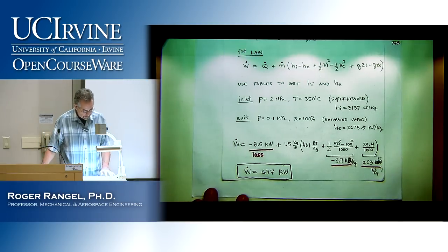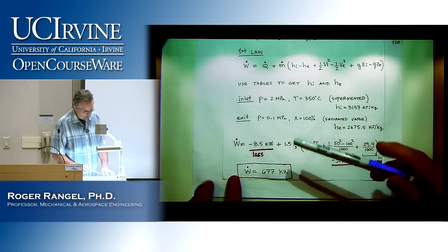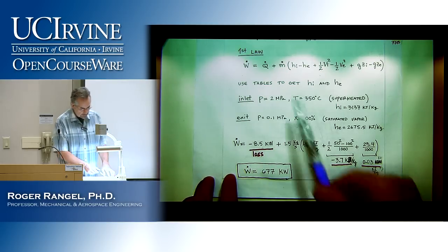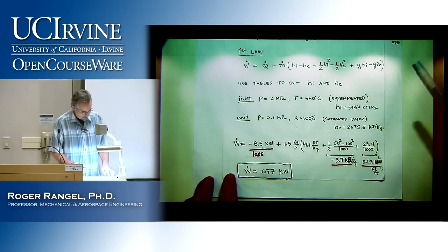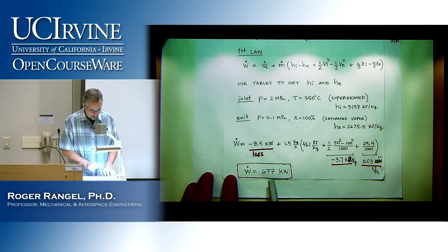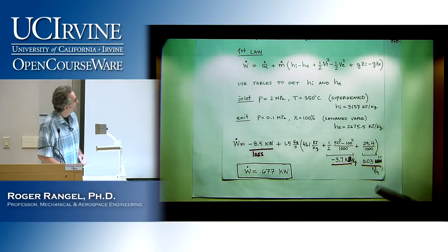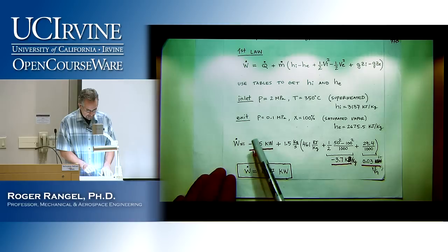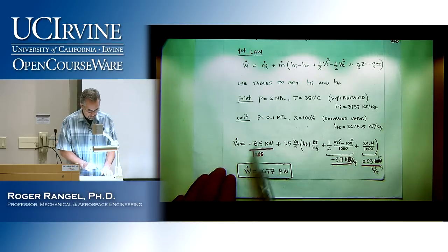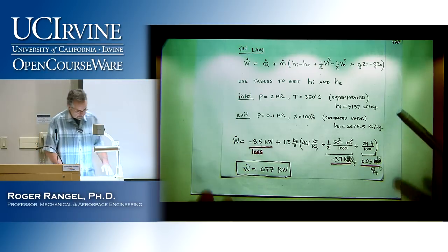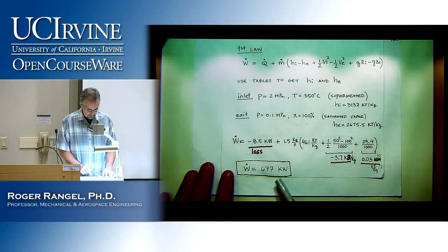And then you can see also here why the table that we were looking at earlier indicates that heat transfer may be neglected. This example shows you that the total heat loss from the turbine is a little bit more than 1% of the total power production. So again, if we had neglected the heat transfer, we would get a result that is perhaps somewhere around 1.5% different. That's not a very significant difference.